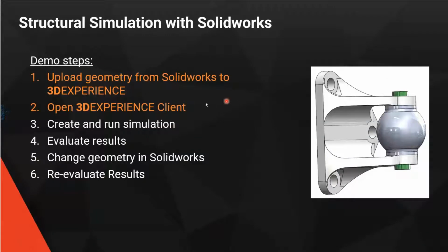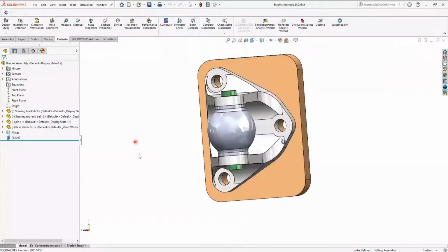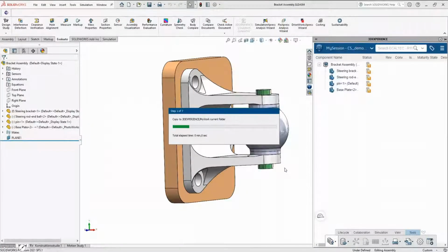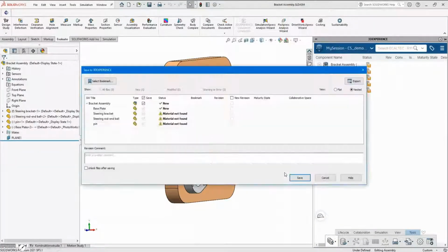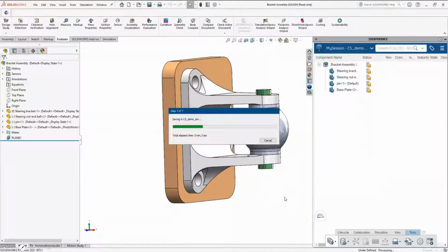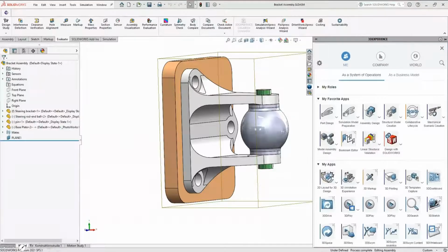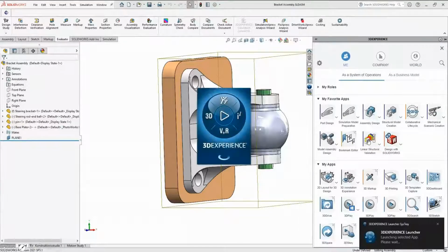So let's go ahead. The first thing you do, this is SolidWorks, sorry, and this is a really useful little 3DExperience download that adds on to SolidWorks, and then you can essentially combine all the features. It has a built-in PLM system for SolidWorks files. So what they're doing now is you save all the parts into 3DExperience. It gets converted into a 3DExperience body, and then through the SolidWorks add-in you can launch and do simulations based on that part.